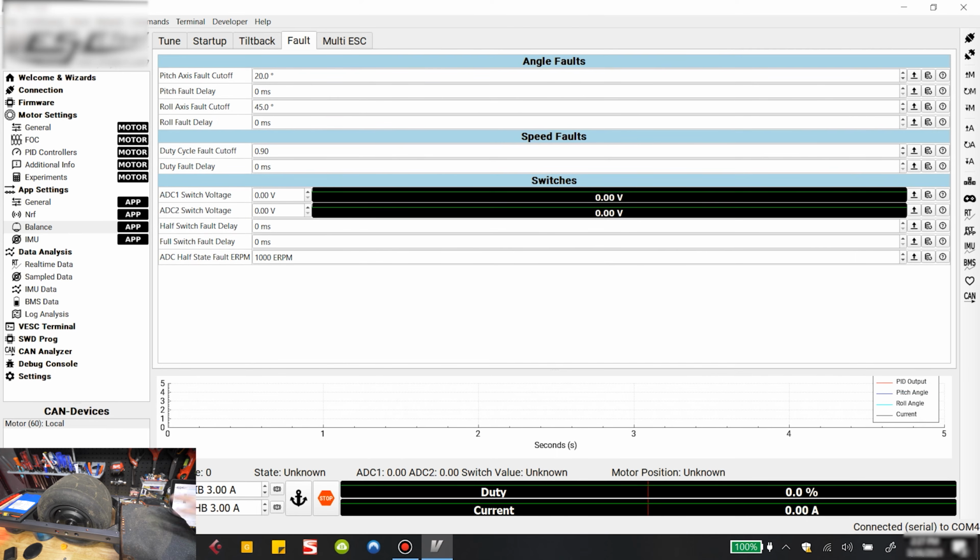So talking about that, here we are with the foot sensors. The foot sensors, just like on a regular Onewheel, are a 2-zone pad. The way this works is that it's a variable resistor that works off of pressure. This is connected to wires, and what the controller is actually reading is the voltage from here.